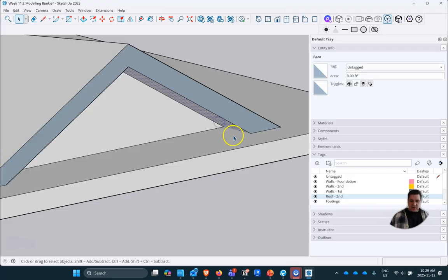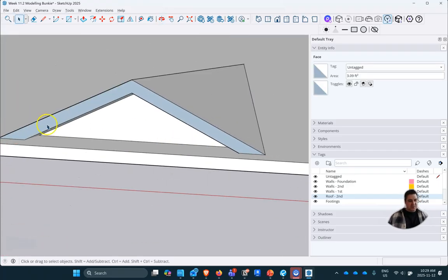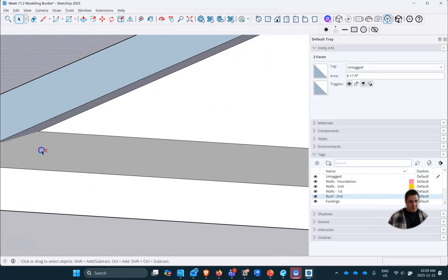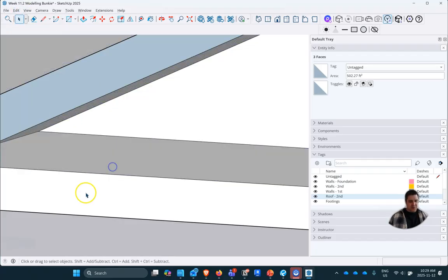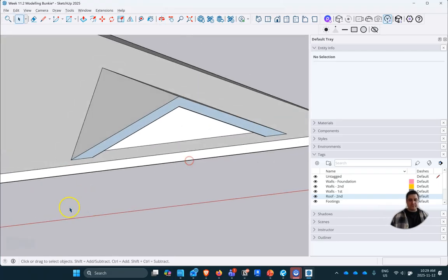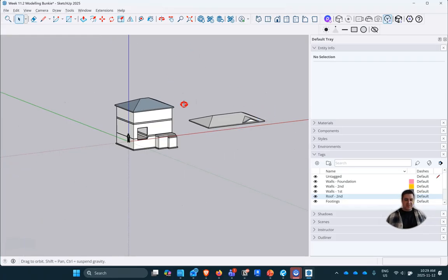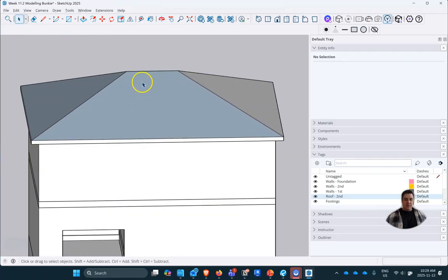And we could actually do in here, we have these soffit conditions right here. So we can do the same thing with those intersecting faces with selection. So that's how to kind of do a dormer on top of an existing roof and make your roof a little bit more interesting. So the last part of this roof conversation is our ceiling.